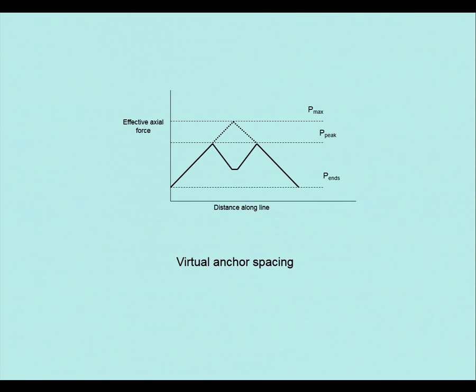Why do we want the pipe to snake while we're doing the selective rock dumping? Well, you might not need to do selective rock dumping at all. There is the other way that you want to make a note of, because there is a way we've just done down in South Africa. Rather than rock dumping and rather than S-lay, we've done a little bit of a snake, but we've put concrete sleepers on, and we've laid the pipe over the concrete sleepers at certain selective points.